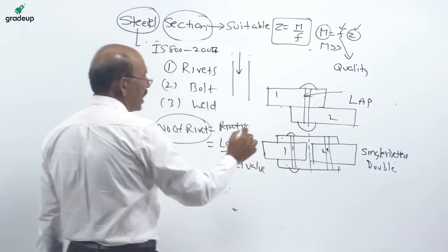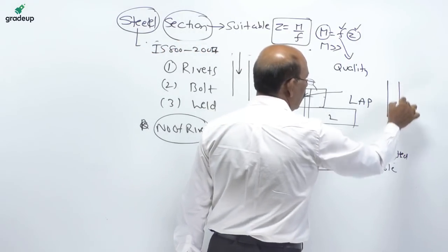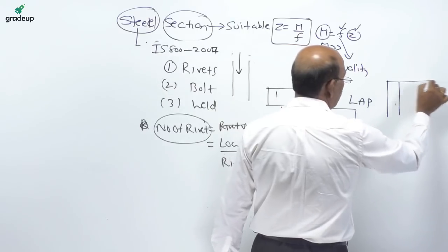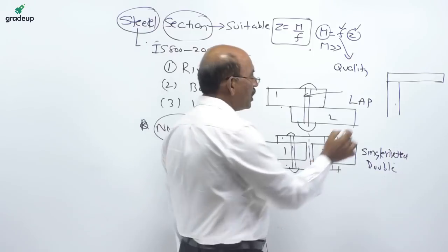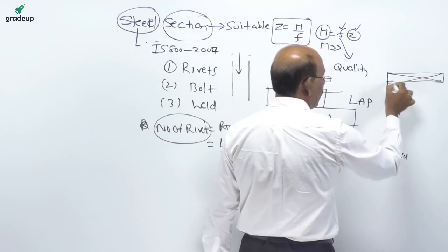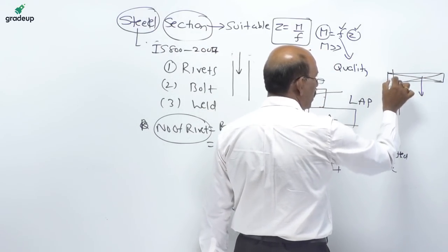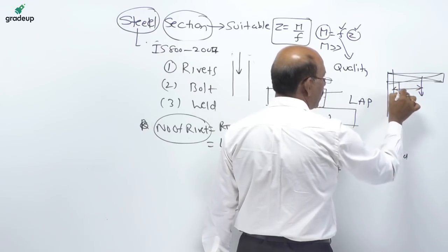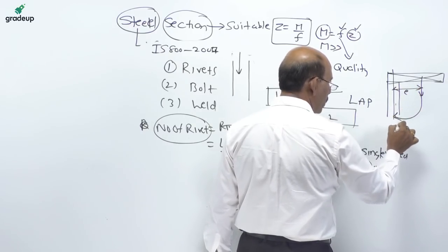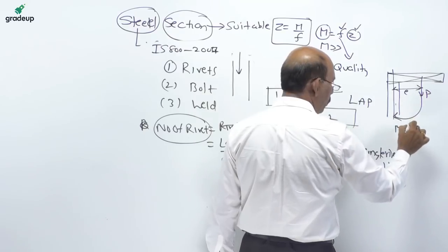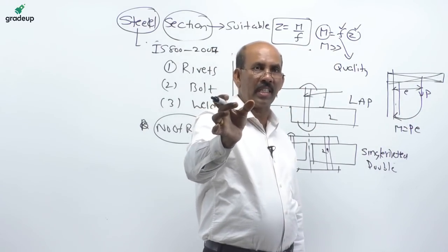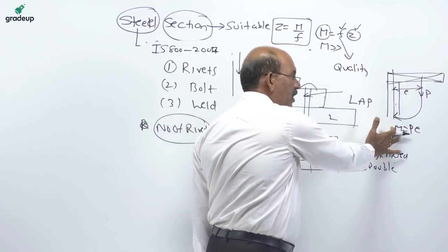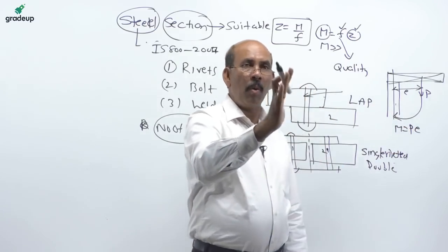Whereas in case of an eccentric connection, this is the column and this is the beam, and we can see that the center of gravity of this one is here, this is the passing load, this is an axis, so this is an eccentricity, so it causes the moment. So, moment is equal to load P times the eccentricity. So, this is with reference to eccentric joint connections, this is the moment existing. In this particular case, moment is free.